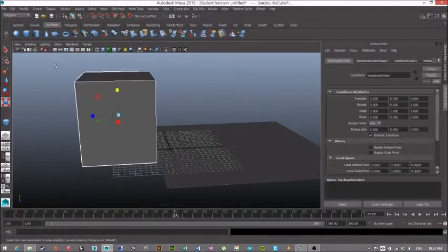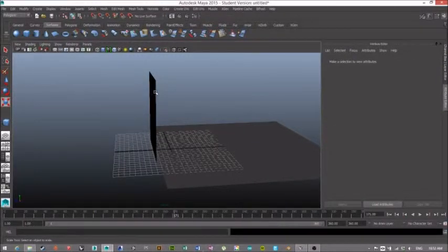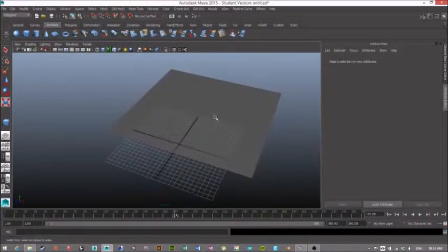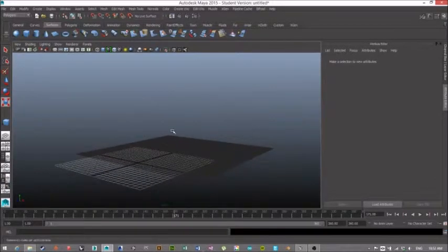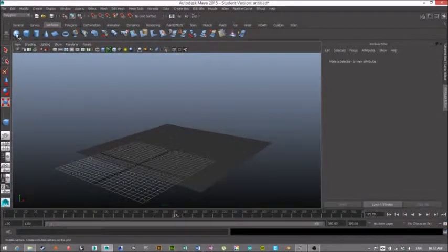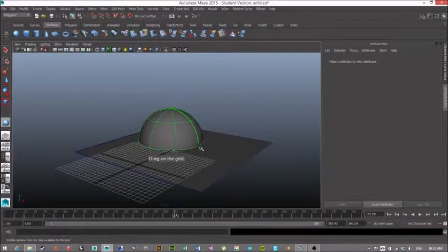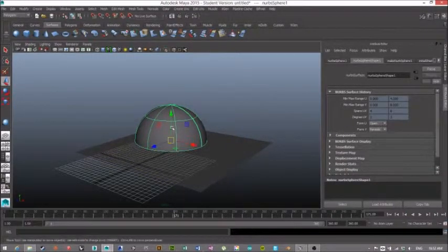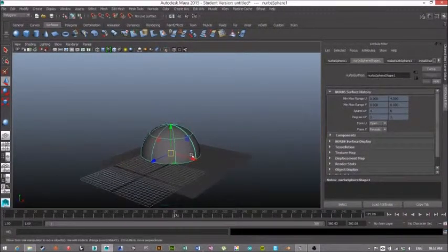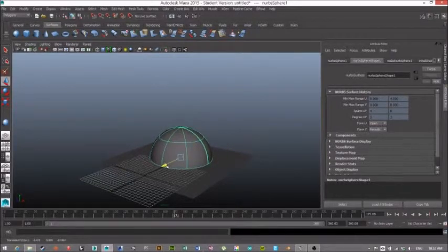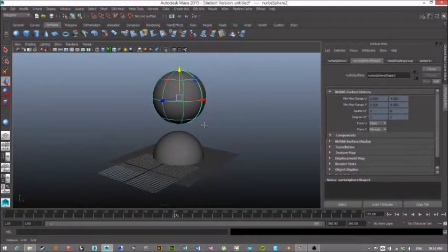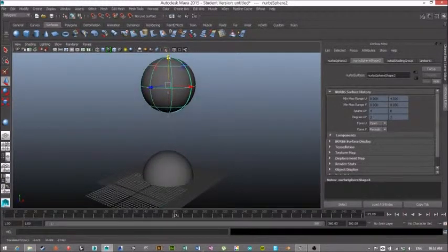Okay, we'll do a blend shape. And I think we'll just do a really dumb example of a bouncing ball. So we've got a ball, or a sphere, we'll say. So this sphere, to make sure that it stays topologically similar, all we'll do is duplicate it. That's in Maya, it's just Shift D. And we'll move one up. Okay, so now we have two spheres that are the same thing.